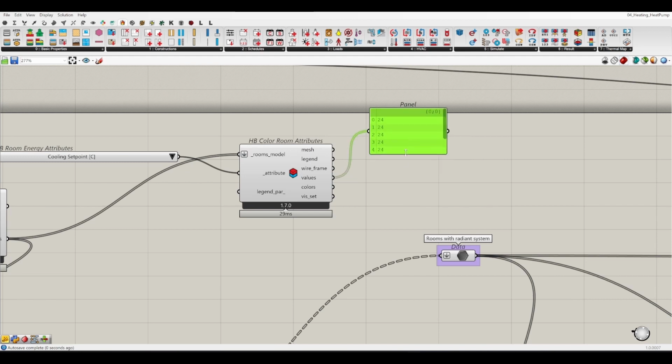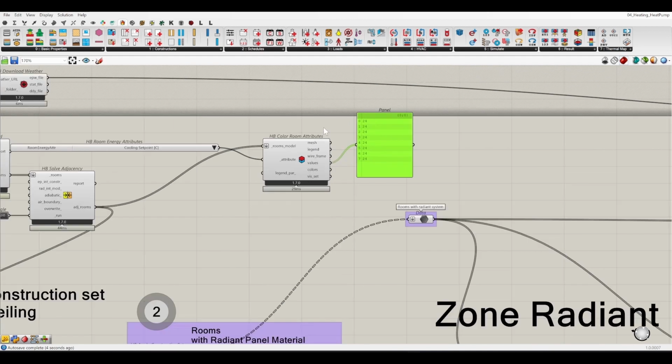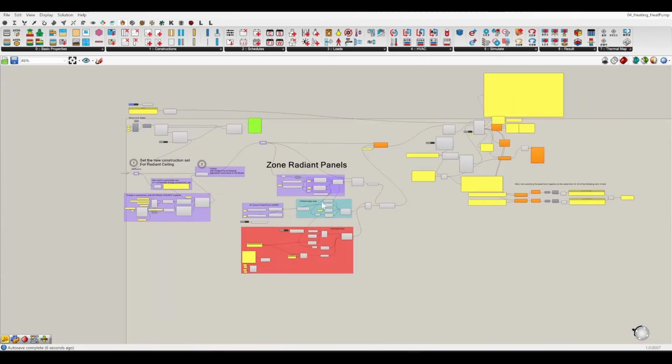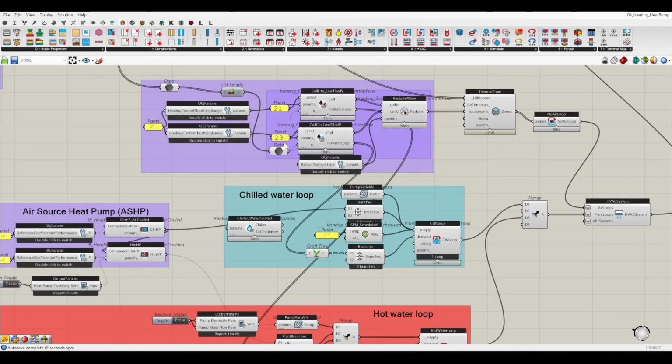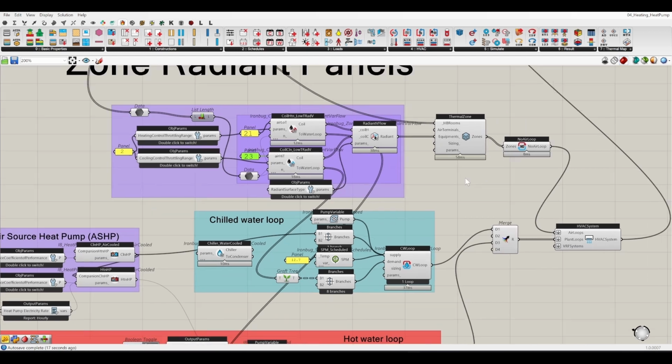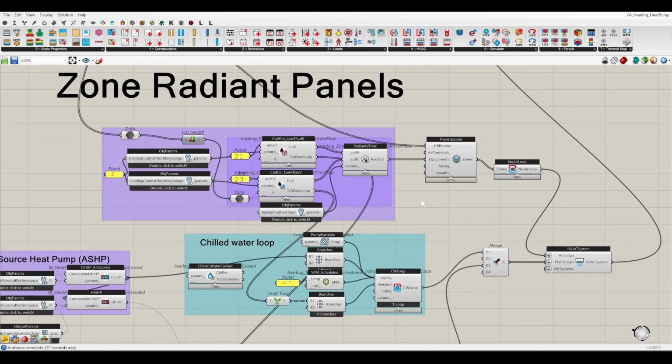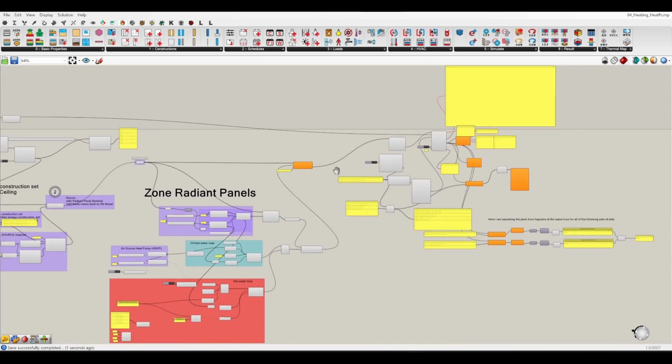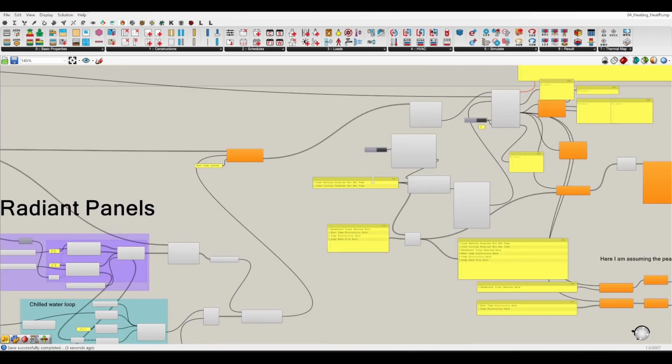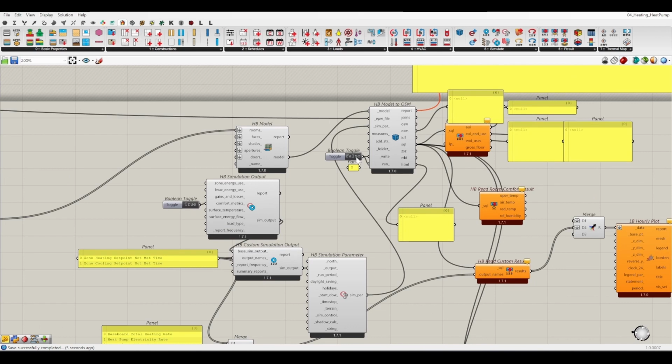Value. So the cooling set point was set to 24, and we were using the 24 as the temperature to turn on the cooling system. So it might be too close to each other. So let's see if this one helps. To 23. Let's run again.